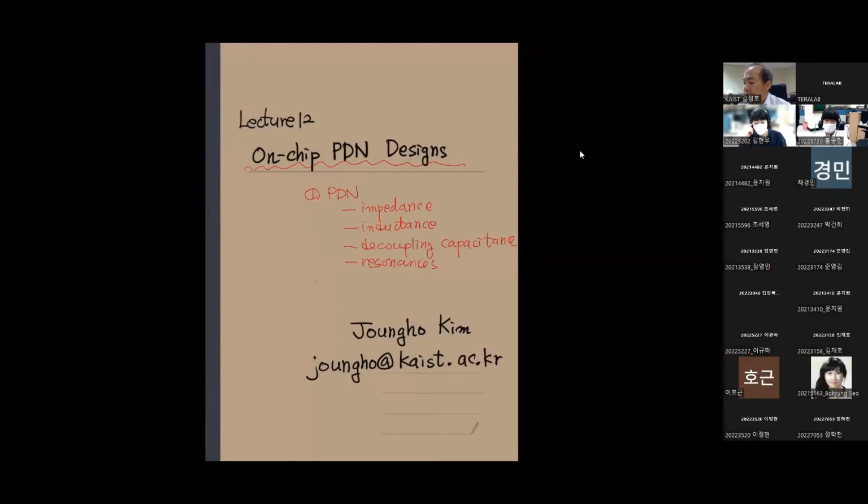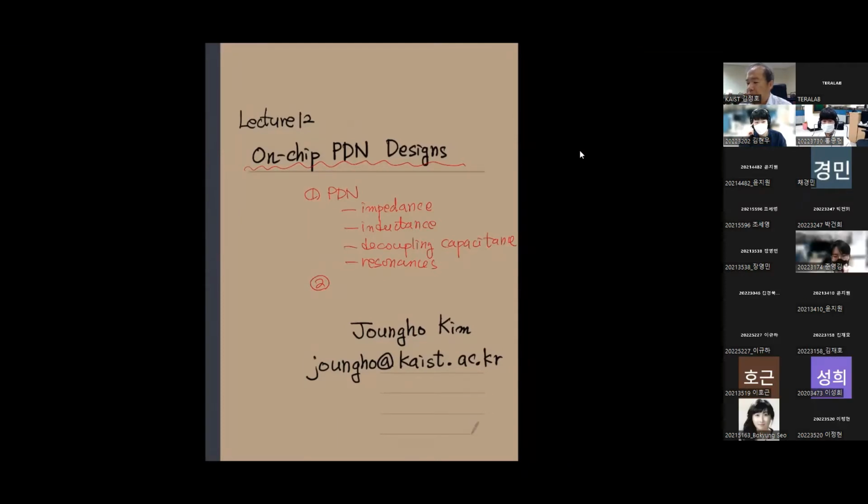Also, I said that we have hierarchical design approaches. On-chip decoupling capacitors are responsible for high frequency fast switching current. Meanwhile, PCB and package level decoupling capacitors have functions to supply the switching current at megahertz to 100 megahertz ranges.